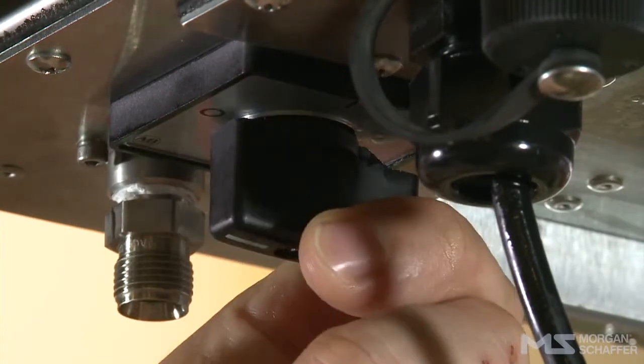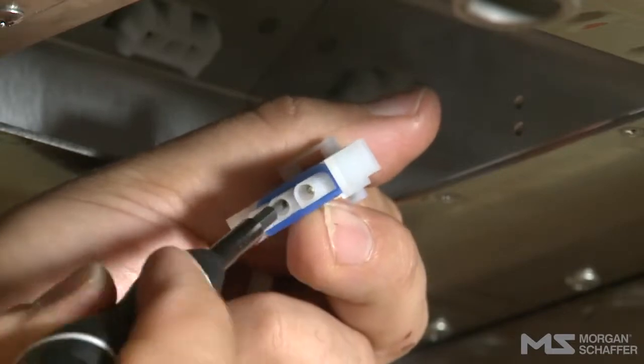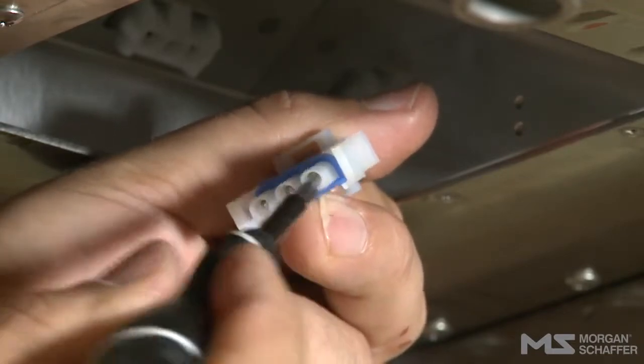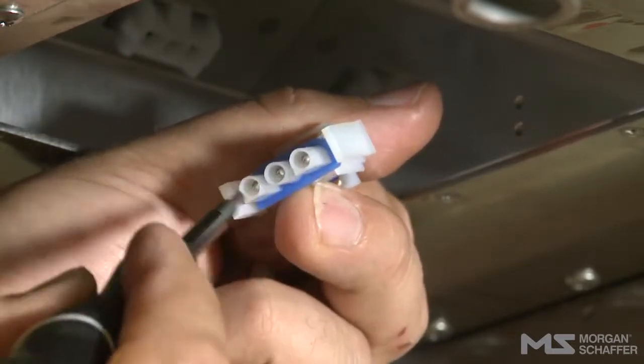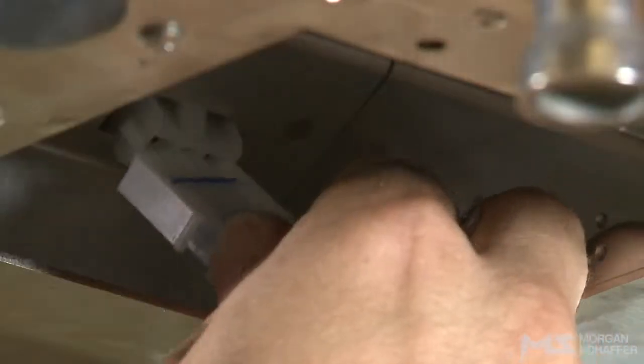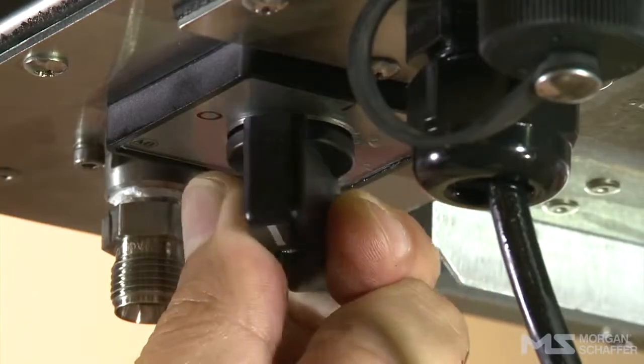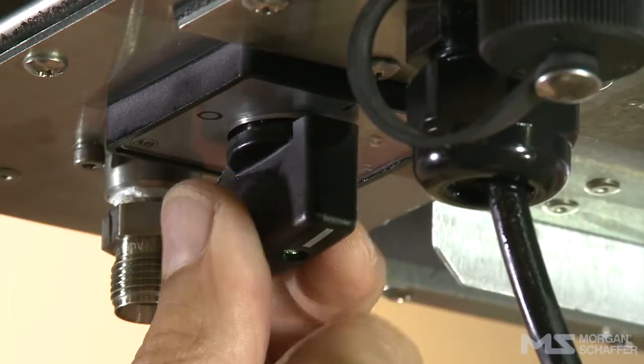Ensure that the external fan is properly connected. Turn off the Calisto. Unplug the fan's connector and ensure that it is clean and in good condition. If not, clean and/or repair it. Reconnect the connector, ensuring that it is fully engaged and locked. Restart the Calisto. If the error persists after 5 minutes, the fan must be replaced.